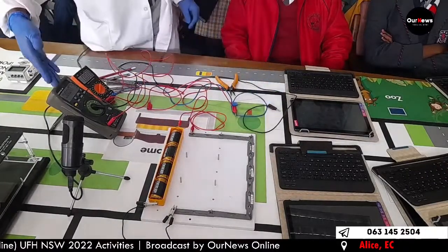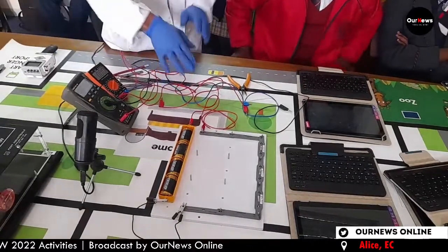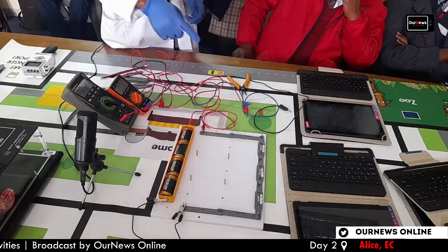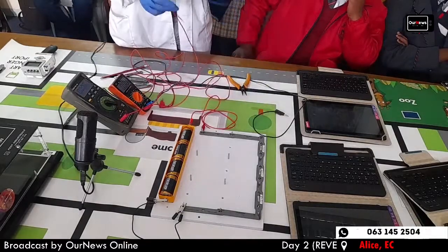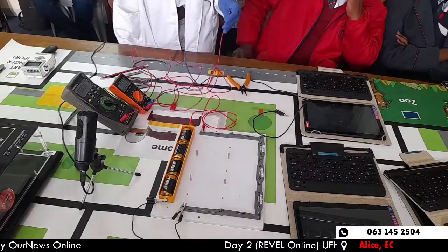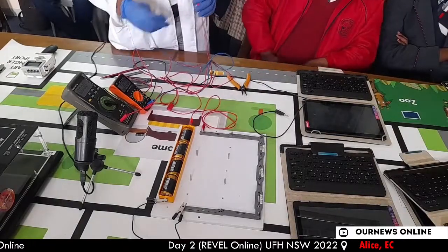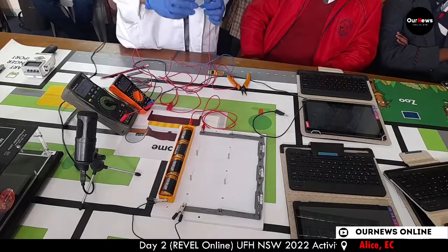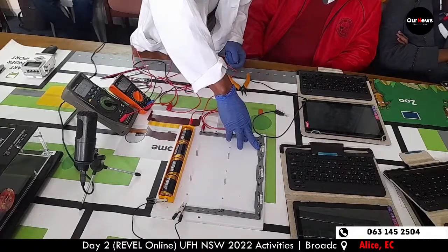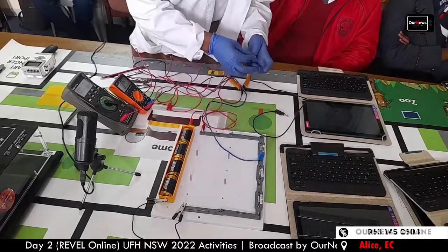So after I've closed my circuit, look what's happening. Both of these multimeters give me 0, 0, because I haven't connected any wire to it. So now we're coming to this one to read the values of the current for each resistor. Okay, so remember we said there's positive, there's negative. The blue one represents the black one also, which is the negative. So remember we said that current is inversely proportional to resistance. So the bigger the resistance, the lower the current. So the first resistor we have here, it's 40.8 ohms. So it's low compared to the others that we have. Then we insert our wires.